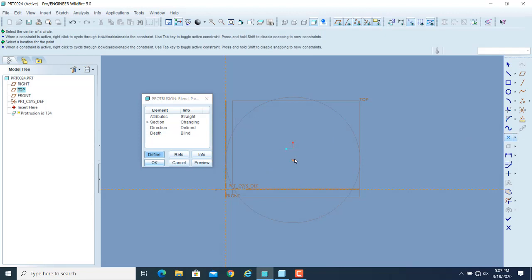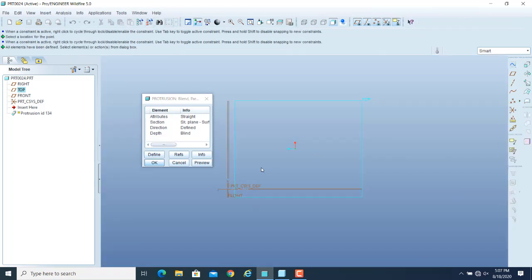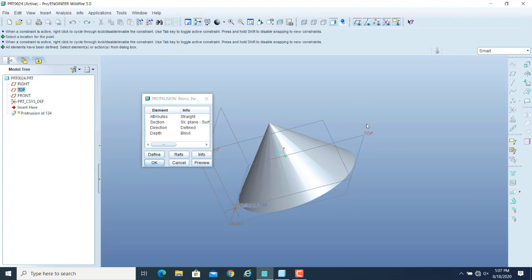So here, let us say at the center point, I define a point, and now I click the check mark button, and if I hit the click key, the circle will be connected to the point. So if you have a point as an entity in the blending option, that point can be joined to any section if it is a closed section.